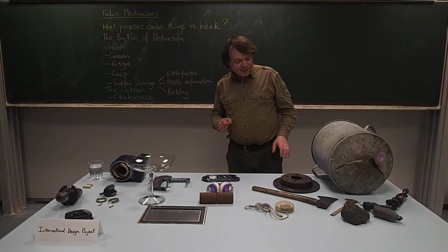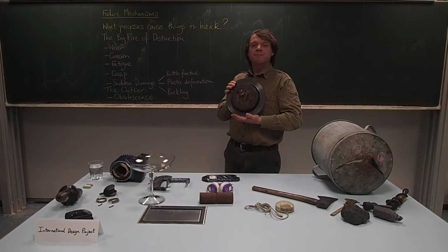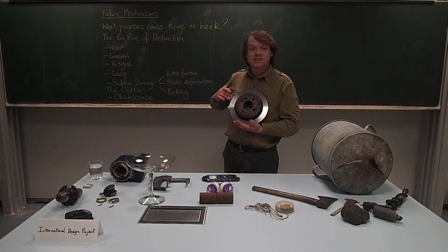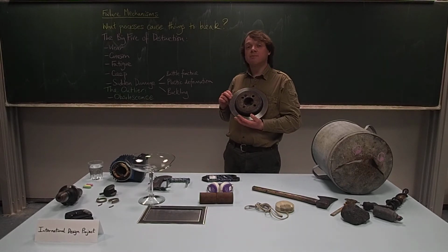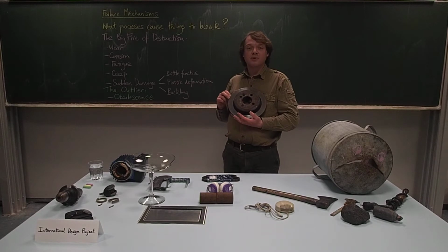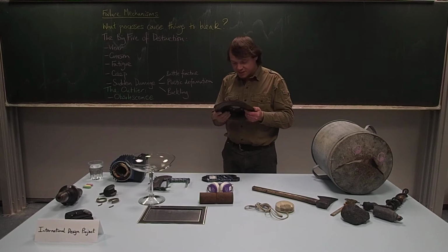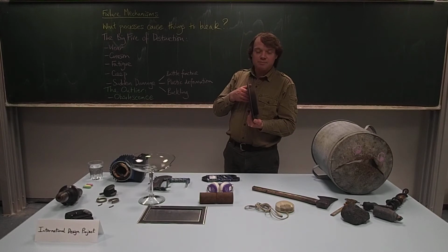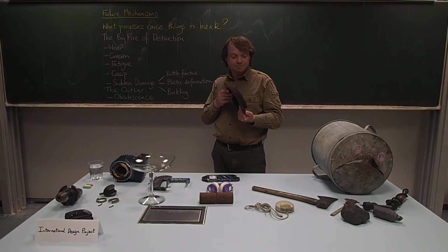Now, here I've got some examples. This is a brake disc from a van, and you can see the surface where the composite brake pads have been touching it is polished to a clean silvery color, and that's the bare steel. Over the course of a few years or a few 100,000 kilometers, this will get too thin. I believe it says on here what the minimum thickness is. Yes, it says 8.4, presumably 8.4 millimeters, and then this will need to be swapped for another brake disc in case it gets too thin and breaks apart.